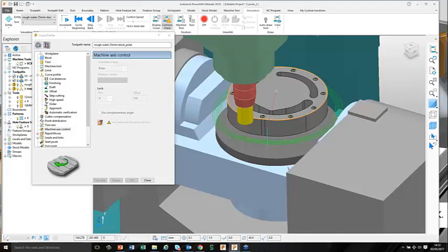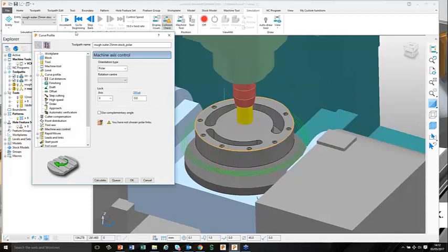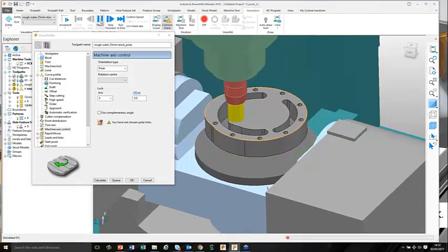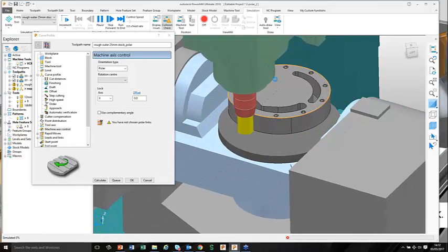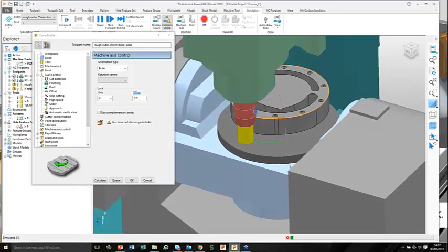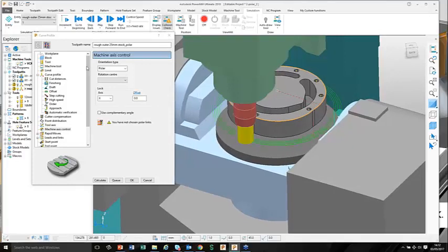So what you want to do is you want to invoke a polar move from the very, very beginning, the very, very start point. Okay, so if we look at the beginning of that, if we play it a lot slower, okay, you can see it does that linear move, it follows it round. This is not a very good example, but you can have problems with it hitting the limits before it actually does that move. So what we tend to do is we want to have these polar links.